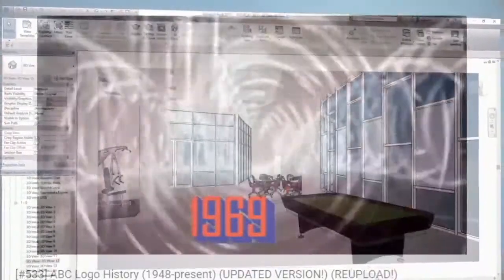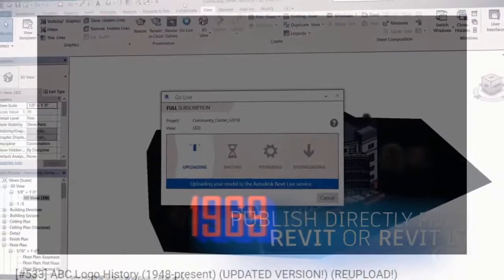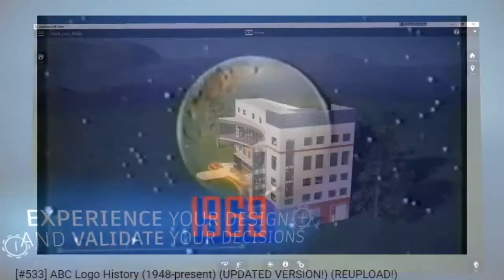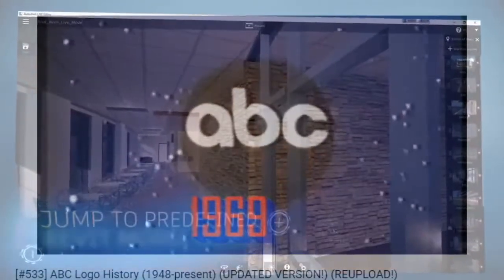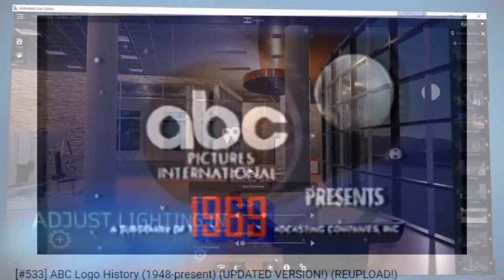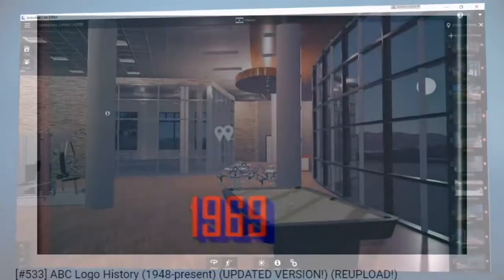Plugging away. Modeling thick finishes. Thicker finish materials such as tile, stone pavers, or terrazzo can be applied as unique floor types and modeled where required. For large areas of finish, such as a public atrium or airport terminal, you can assign these materials within the layers of the floor assembly. When you need to add smaller areas of thick floor finishes, you may encounter one of two scenarios, with a depressed floor and without. In areas such as bathrooms, a thick set tile floor may require the structural slab to be depressed in order to accommodate the thickness of the finished material.